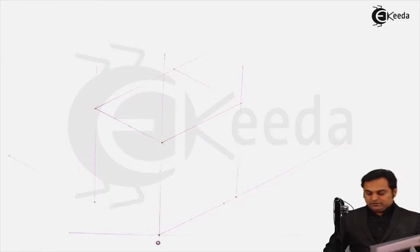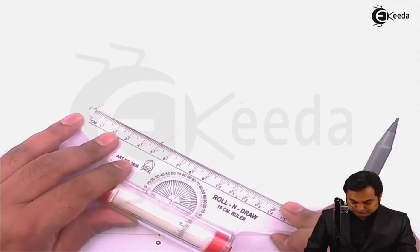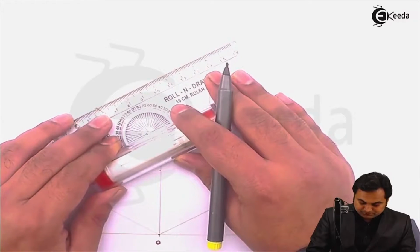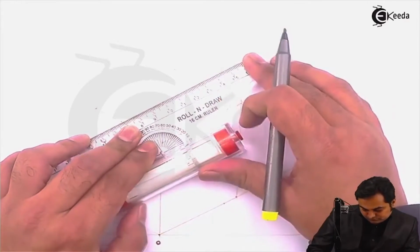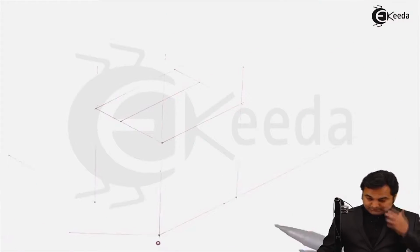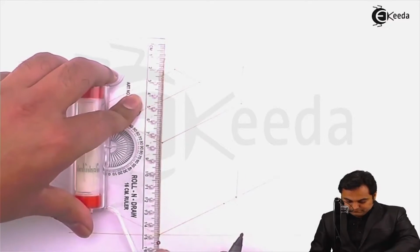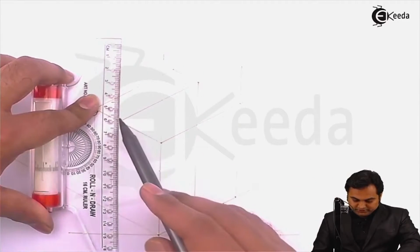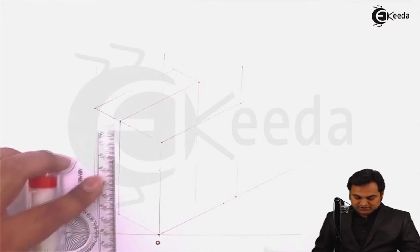For that, here I'm measuring the width as 20 mm and then drawing a light line parallel to the length. Next, I will be projecting these points with the help of vertical lines. Light vertical lines. Then measuring a height of 52 mm.